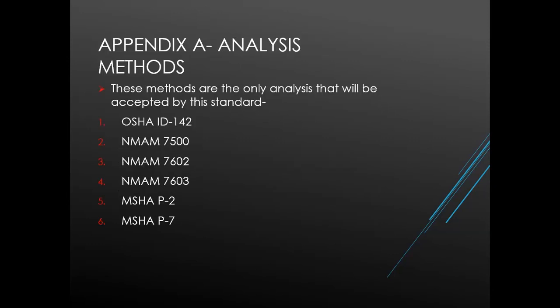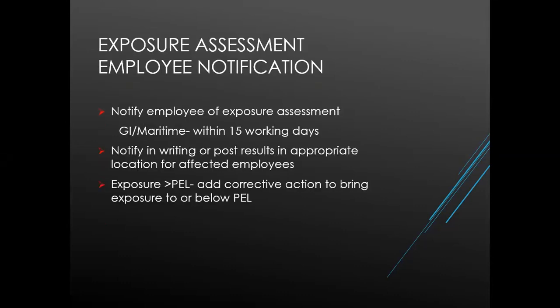All exposure samples that are taken must be evaluated by a laboratory that analyzes air samples for silica in accordance with the procedures in Appendix A, which are shown here. Employees must be notified of these sampling results within 15 working days after completing an exposure assessment. The employer shall also individually notify each affected employee in writing of the results of that assessment or post the results in an appropriate location accessible to all affected employees.